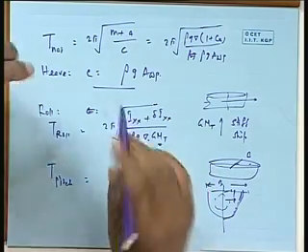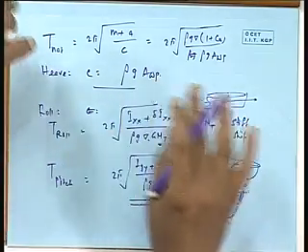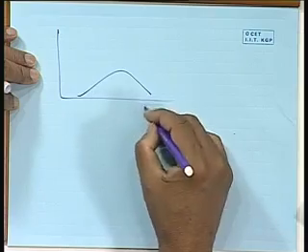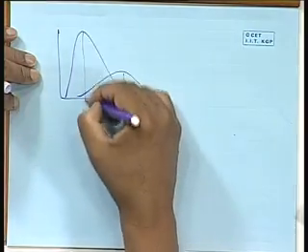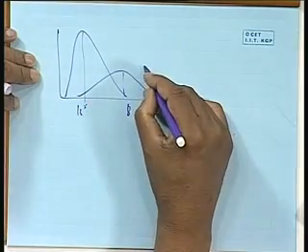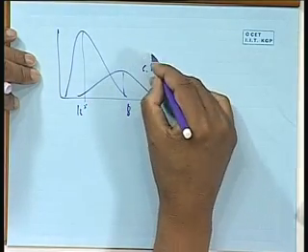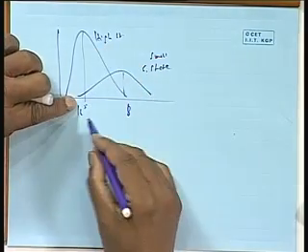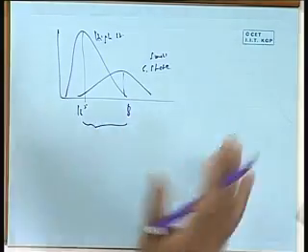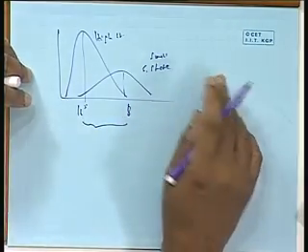Why do I mention that? Because it turns out that for a typical shape, all natural periods happen to be somewhere between 8 to 16 seconds. Now you take a small sea state and a large sea state. This may be about 8 seconds, this may be about 16 seconds. What I mean is that from very small sea state to very high sea state, the peak is between 8 to 16, and my natural periods are also within that range. You see, it is not very different for a typical shape.